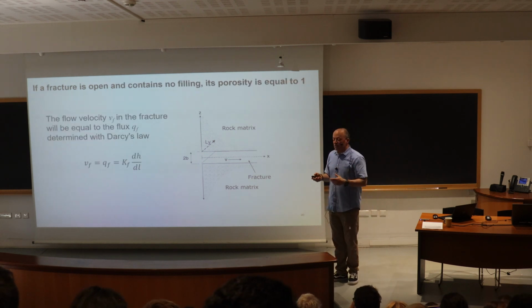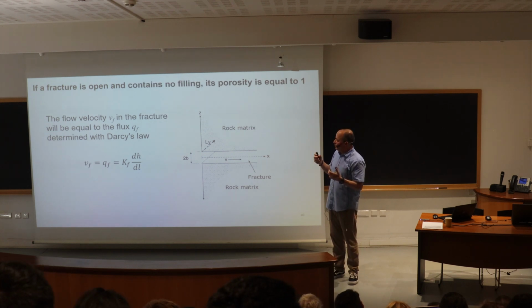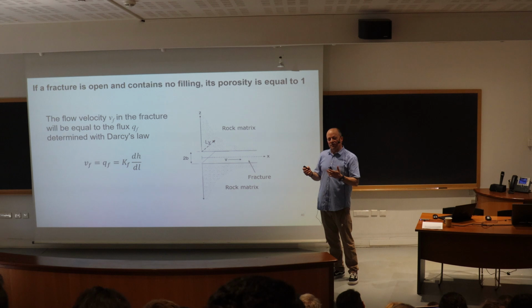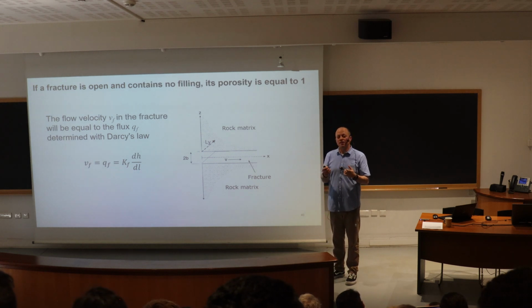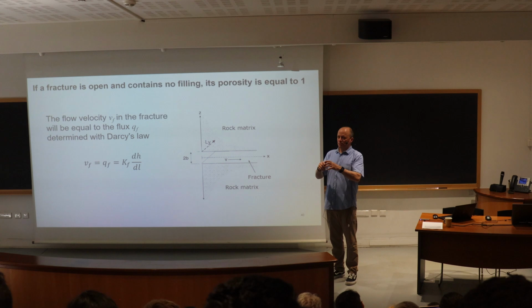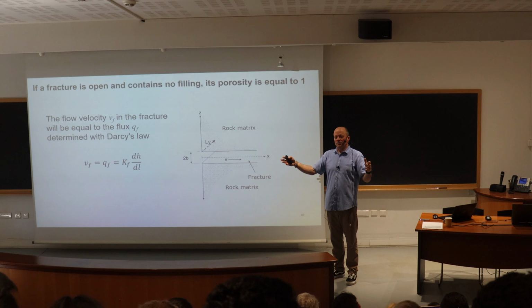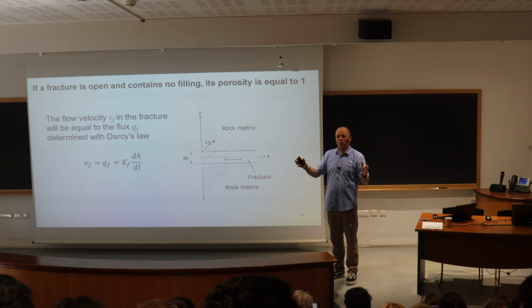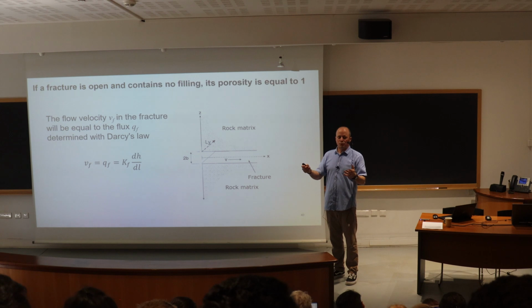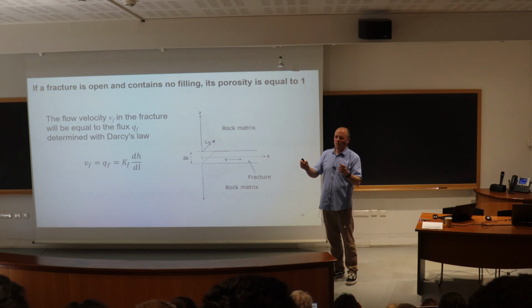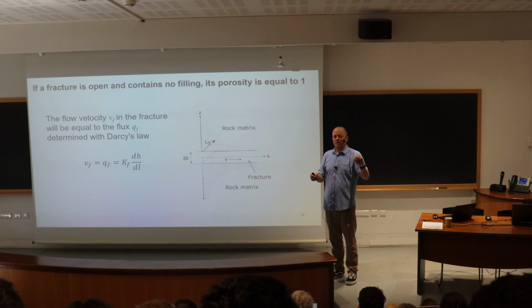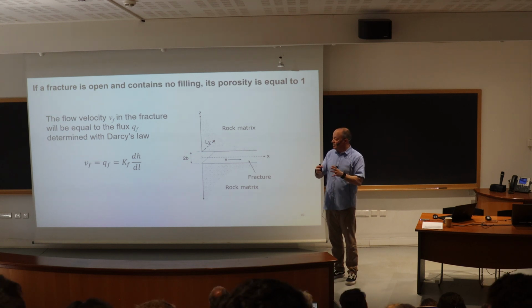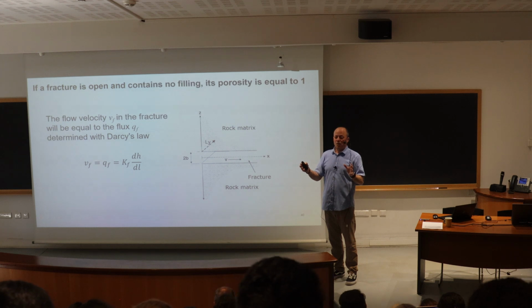The porosity in the fracture is often assumed to be 1, so it's an open fracture. But there's some variations that exist. There's applications where people will generate the distribution of variable aperture for a single fracture. There's people who've done measurements in the lab because fractures are not parallel plates, and they will use the same upscaling approaches to get effective porosity for the fracture, which might be different from 1 because fractures might close at some locations, open elsewhere, and get an equivalent hydraulic conductivity for a rough walled fracture.